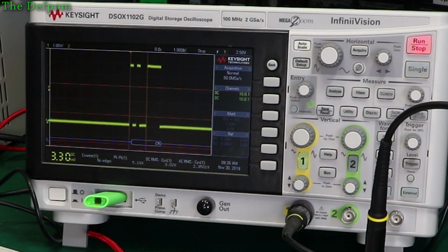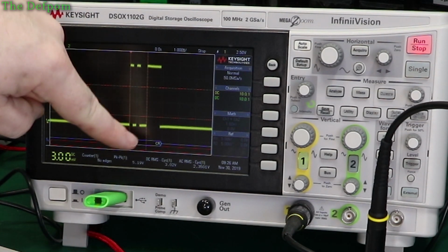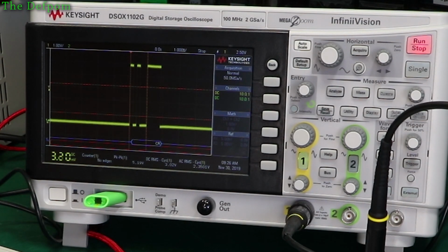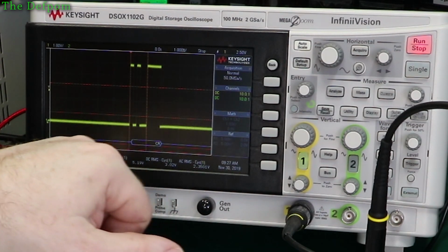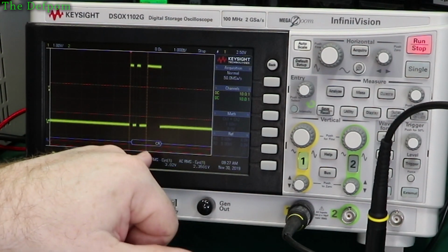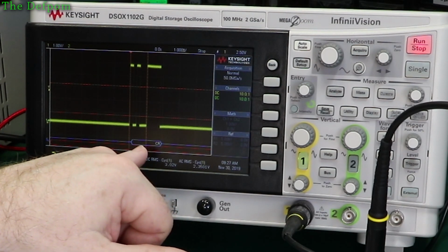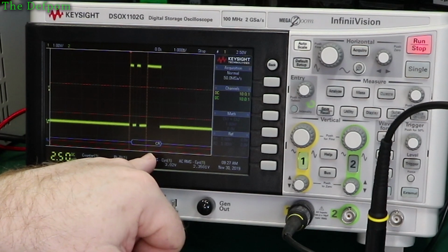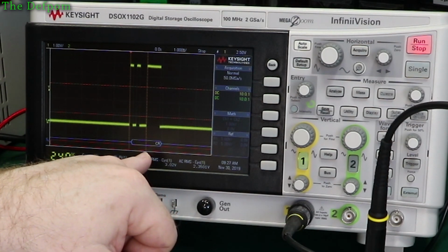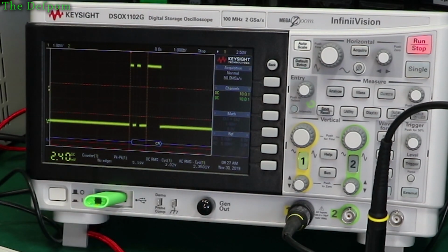Now that's all it puts out when you start the timer. When the timer first starts, that's all it puts out, which is translated into a carriage return, or decimal 13. This is actually doing ASCII decoding at the moment. This particular scope will actually convert those into the special characters. So if it knows a special character, like decimal 13 is a carriage return, it tells you it's a carriage return rather than just leaving it blank. Some scopes will not do that. They'll just have a blank section and you won't know what it's actually sending.